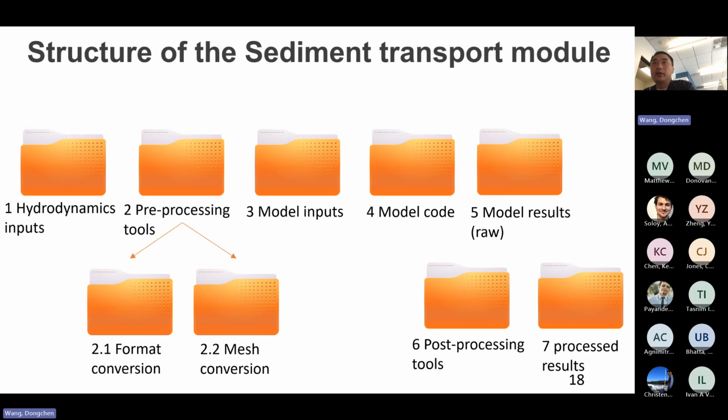If I understand correctly, Dorado does not give the land accretion rate following the hydrodynamic condition, right? That's correct. And this sediment transport model is more like a standard way to solve sediment transport theory, and that will give the exact land accretion rate, in terms of, for example, meters per year.